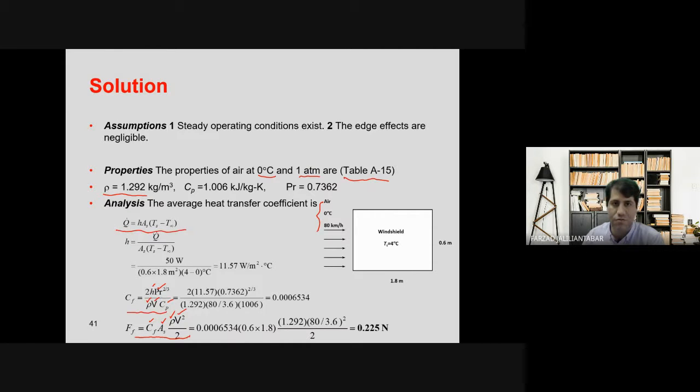We have this equation, if you remember, for convection heat transfer. If we restructure that, h can be calculated by this equation. But do we have the information to calculate h by this equation? Let's see. T infinity, 0 degrees Celsius, given. Ts, 40 degrees Celsius. We have As, the dimensions are given, so we can calculate that. How about Q dot? Q dot is the power here, because we have a steady operating condition, which means these 40 degrees Celsius remain constant, these 0 degrees Celsius remain constant.